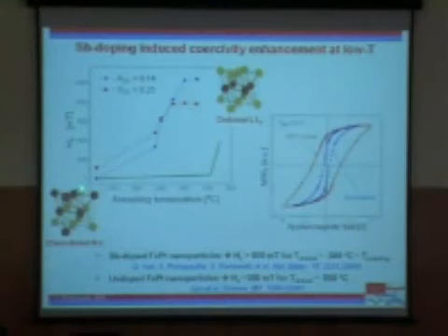So when I plot the coercivity as a function of annealing temperature, let's look at the green cartoon that I've drawn over here. You need to go to about 500 degrees centigrade in order to get the high coercivity phase. By then you're destroying your assembly, so it's useless.